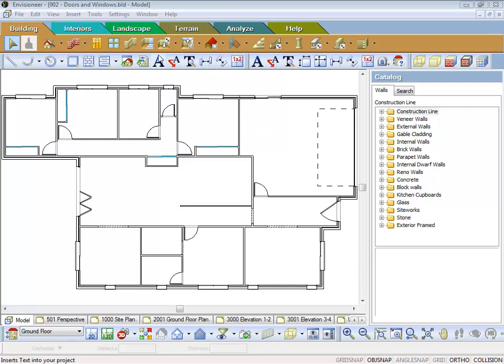In this lesson we're going to cover ceilings. Basically ceilings are the same as floors. You can put them in by room, by perimeter, or by picking points. Now first of all, with perimeter you can just pick the surface and then pick a point on the floor. You can do it in 3D as well, so I always want to show you how that happens.